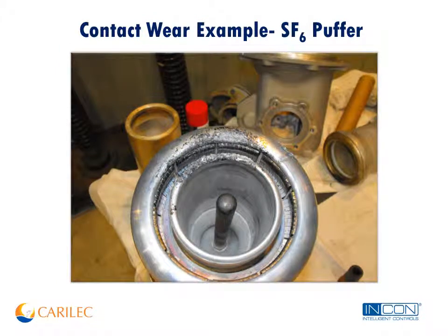All right, here's another view of that moving contact. As I said, the round contacts around the outside, those are the mains, and that prong in the middle is the arcing contact, and that is really what should be taking the brunt of the arcing. We don't want to see arcing on the main contact because it can be really bad really quick. So the arcing should be confined to inside and on that prong alone. It's a sacrificial contact, as they say.